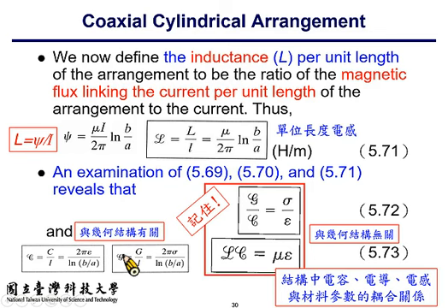conductivity for the conductance. Interestingly, if you do some manipulation over the L, C, and G values, say taking the product of L and C, you find that the influence of the geometric parameter is cancelled out. It only leaves mu times epsilon, the product of permeability and permittivity.